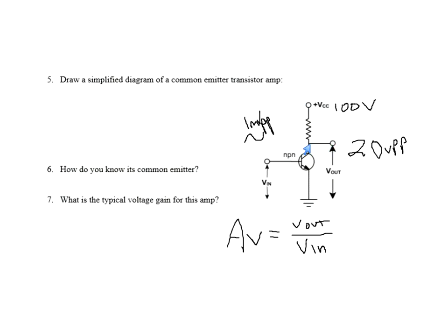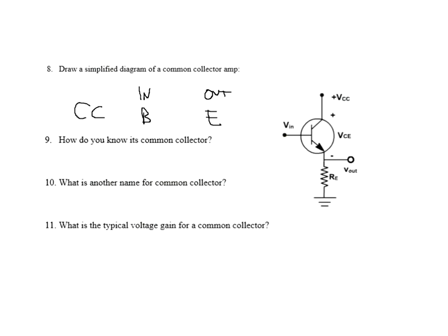That's what allows us to use the output off the collector, because you probably learned the power supply is an AC ground, even though it's providing DC. So you have to have a resistor in it. In a common collector, you're not getting the output off of the collector. The collector is tied to AC common, which is VCC. That's why it's called a common collector.